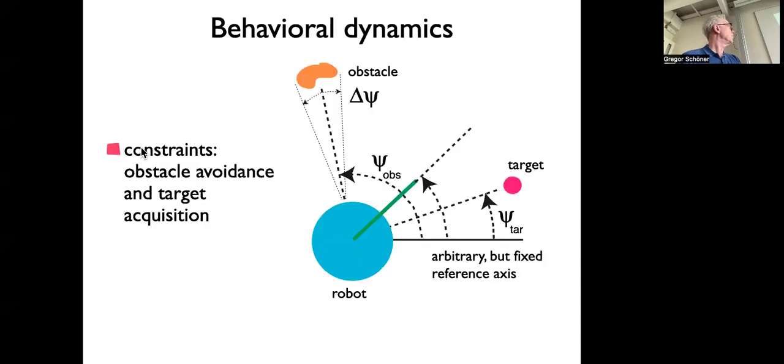So last time I talked about behavioral dynamics as this dynamics of obstacle avoidance. So the notion is that if you have a vehicle and it has the heading direction as a dynamic variable against some arbitrary world axis, then you can express constraints like going to a target or avoiding an obstacle as desired or undesired values. That's a very general feature. Almost all approaches to vehicle path planning conceive of things this way, that some steering angle or some control variable has desired and undesired values.